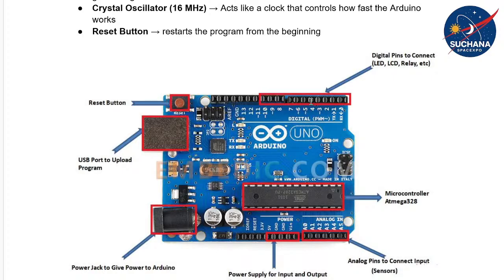Here you connected the longer terminal to pin number 7. By default, pin number 7 does not carry any voltage. It's like a floating pin. Once you configure pin number 7 as an output pin in the embedded program, the microcontroller will route this pin to the 5 volts.